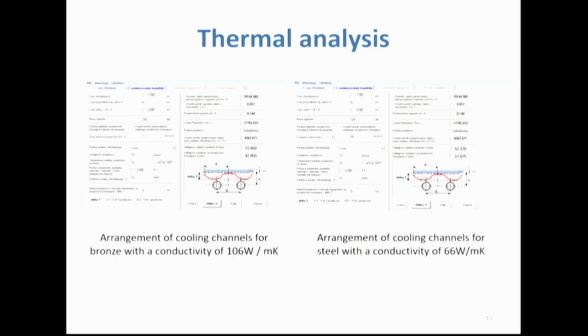So, the next step is the thermal analysis. Because maybe you are asking the question, why, if the analysis shows 230 tons, everybody is producing on a 450 ton machine? The answer is that this typical mold for the mushroom crate is quite big. So our idea is to make it much smaller to fit the smaller machine. And the way to do this was changing the mold design, especially the slides.